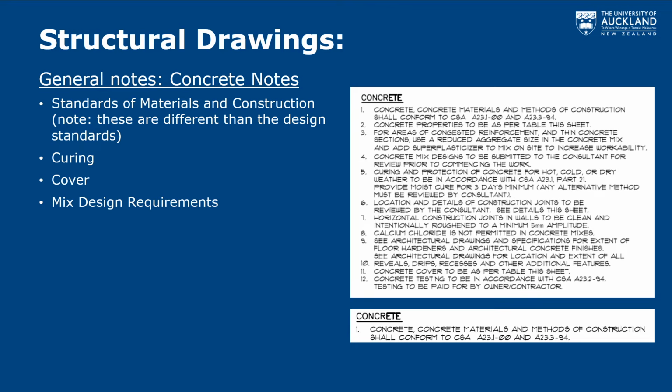And this is maybe a good time to say that a lot of these general notes are common from job to job. And so you'll see them getting recycled from one set of drawings to another because most of how we build things has been standardized. How we place concrete on a job site is quite standardized, and we just need to make sure that it's there. But it is important to know that if you, as a new engineer, are going to come across this, you want to make sure you're not just blindly copying general notes which refer to one job onto a job in which they're not applicable.